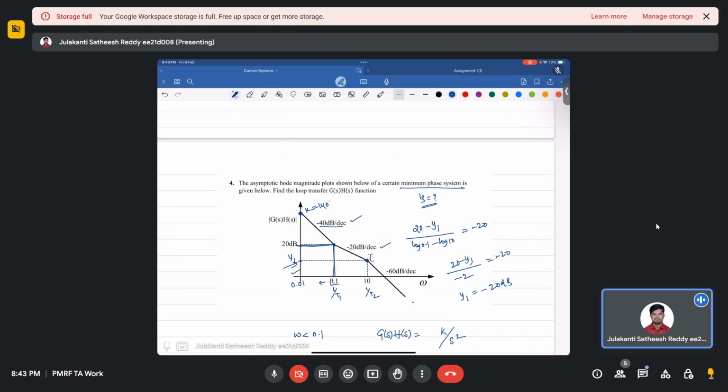See, this one only happens because of the first order. Two poles at origin. Now this one is one pole, because you know that from here to here the transition is only adding 1 zero. So this is clear and this is clear. Now from here to here there are two poles, whether it is a second order like s square plus 2 zeta omega n s plus omega n square format, or s plus p1 whole square format. Two poles at the same frequency. So if they give such a way, they have to mention the zeta. If they are not mentioning it, blindly you take it. Agree?